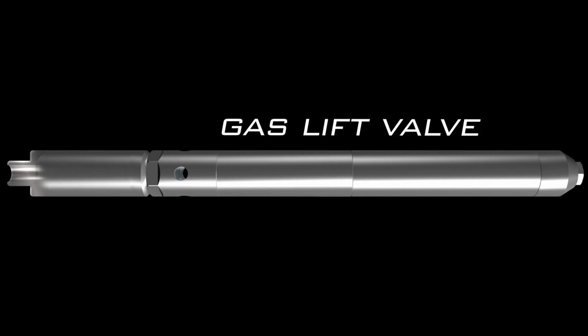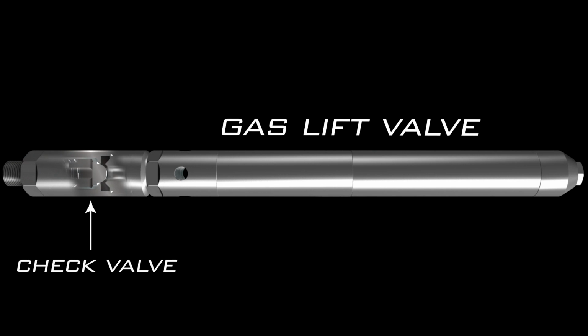Employing a metal-to-metal seal, the check valve protects against backflow from the tubing to the annulus. This type of spring-loaded check valve is used with gas lift valves that do not have an integral check valve. The mandrel is the backbone of the PCS Opti-Flow gas lift system. Multiple mandrels are installed at specific depths as an integral component of the tubing string. The ported lug of this tubing retrievable mandrel is used to house the gas lift and check valves.